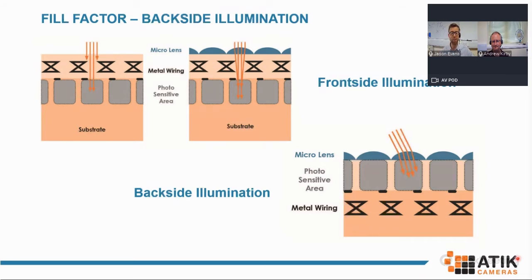Also, whilst we're looking at these images, we want to quickly note dynamic range, certainly whilst having just noted full well depth. Full well depth can impact dynamic range depending on how it's calculated. The dynamic range in essence is the value that helps to indicate how many different shades of, well, for a mono sensor, how many different shades of gray a sensor can represent.